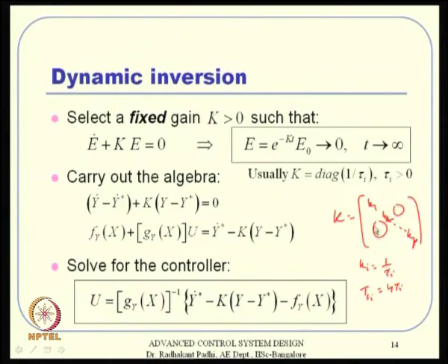Okay. So, my strong suggestion is always to operate from time domain specifications like this, instead of looking at your behavior later and all that. If you want to implement this control in any problem, start with some specifications like that, then reverse compute your gain, that should go into the diagonal elements actually. So that this error dynamics will continuously satisfy this kind of settling time property actually.